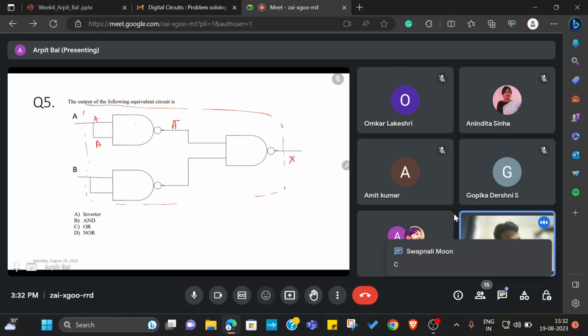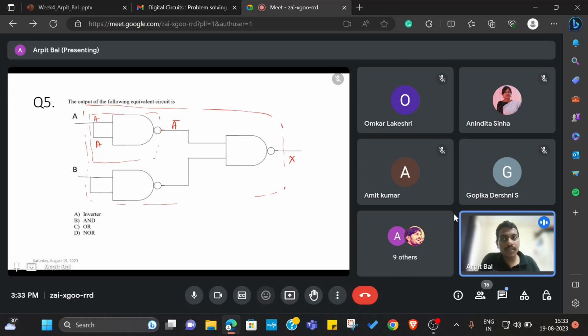So basically in this particular scenario, what is happening is the NAND gate is behaving as a NOT gate, right? So whenever you are asked to implement a function where you need a complement but you are only supplied with NAND gates, what you can do is you can take the value and apply the same value to both the inputs, and you will arrive at the NOT gate.